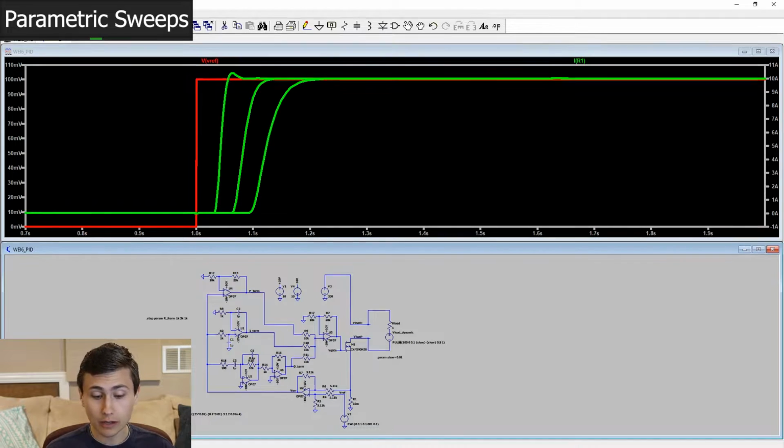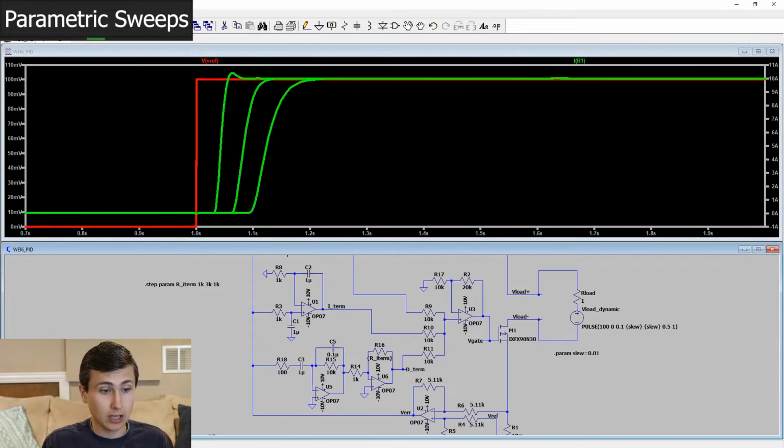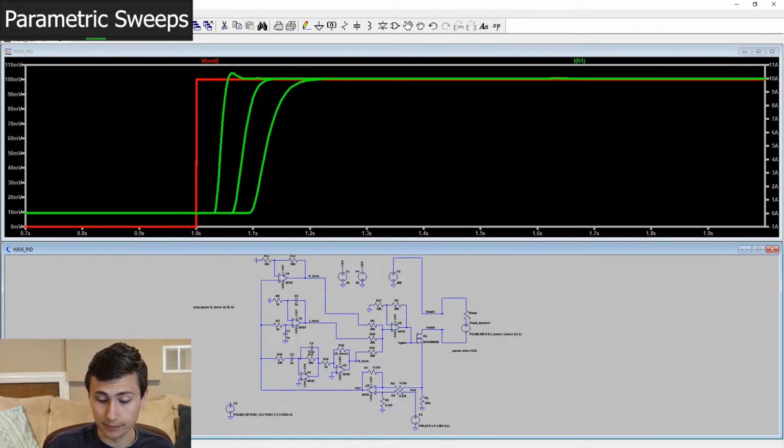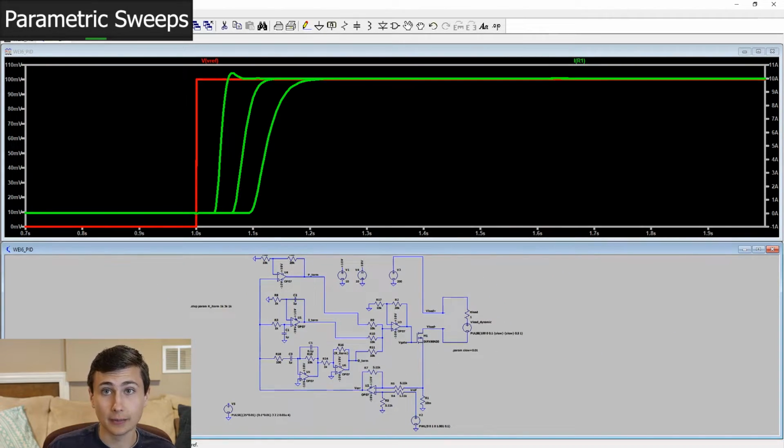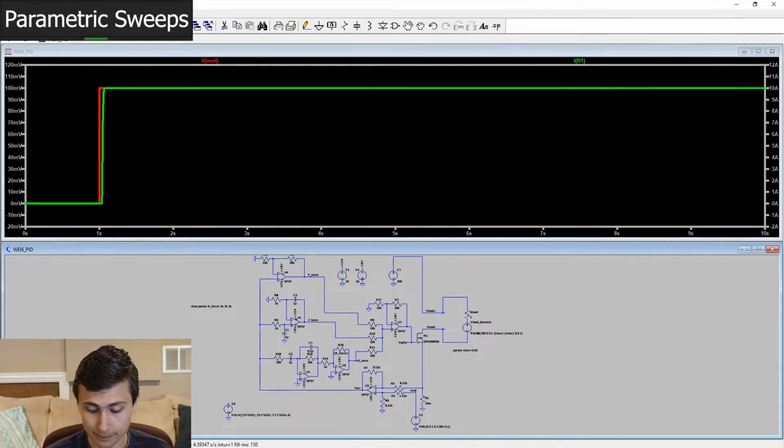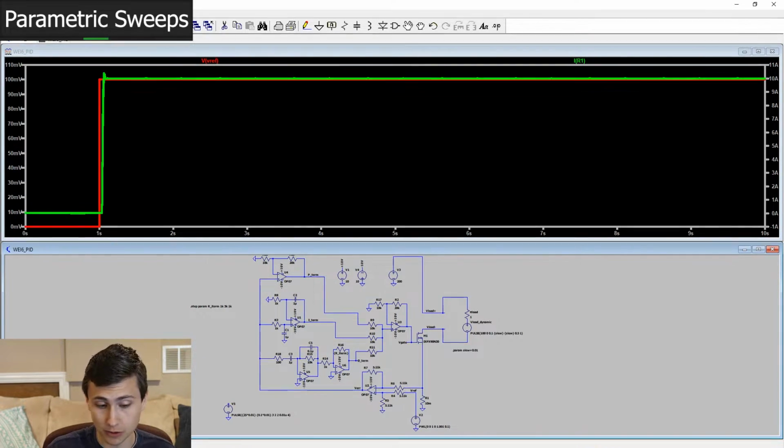But if that's what we want, if we're really shooting for aggressive transient response and we don't mind a 5% overshoot to respond twice as fast, well, hey, let's keep that. Let's keep that 1K resistor and try tweaking a different value. We're going to apply that same step to our D term. So now with our I term kept pretty snappy, let's run 3 steps on the gain of our D term and look at what our options are for transient response.